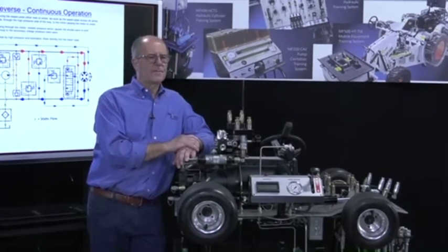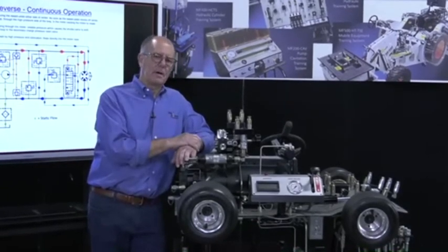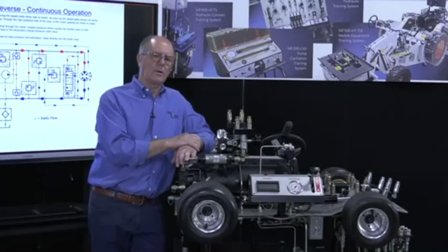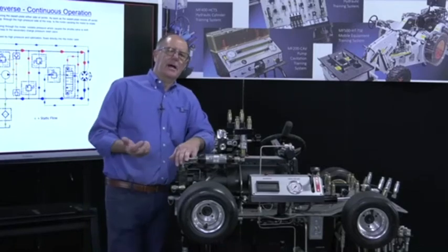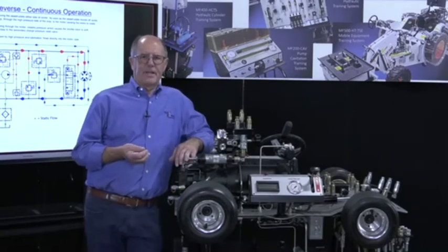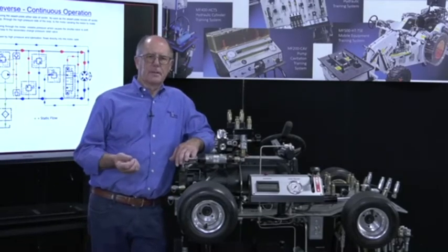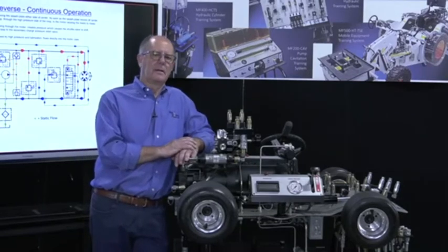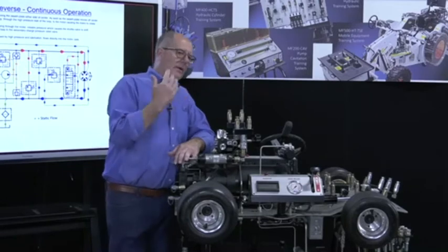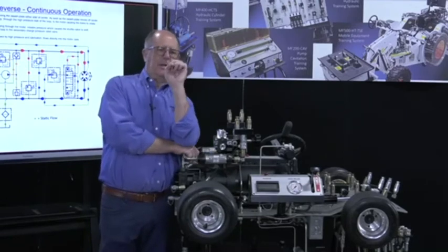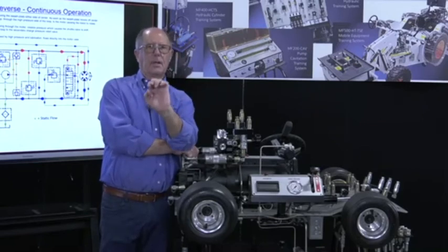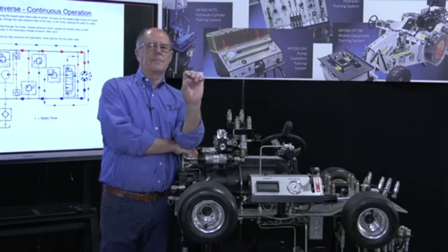In other words, unless you wind up with virgin rubber, you've still got an oil film in the hose, and the oil film will hold contaminants. Besides, if you fire a projectile through a line that's got shrapnel in it, it's going to push the shrapnel into the hoses. It's going to leave pieces of the projectile behind. And then one of the recommendations when using projectiles is that you always shoot 2 through. 1, after you cut the hose, and 2, after you've crimped the fitting.